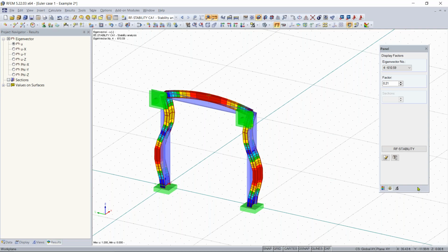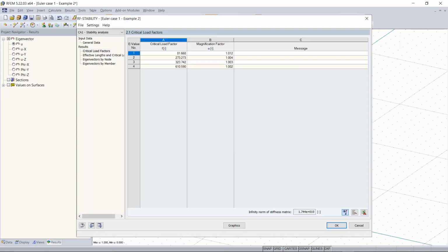I can answer that. I think there are some conditions within the Eurocode, for example, that if the critical load factor is less than 10, a second order analysis should be run. And if the factor is less than, I want to say 2 or something, then the structure needs to be redesigned. But this is all code specific. Within the AISC, we do not have requirements that I'm aware of. So it all depends on which code you're designing to. Thank you for that clarification, Amy.